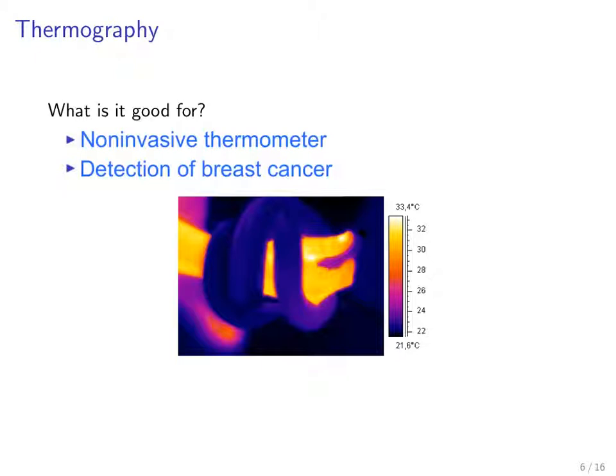So you can build a body-mimicking phantom with similar electrical properties to the tissue at those RF frequencies at which the scanner operates. And then you can use a FLIR camera or something like this, essentially implementing thermography, to detect whether or not you are heating that phantom up beyond safe levels.